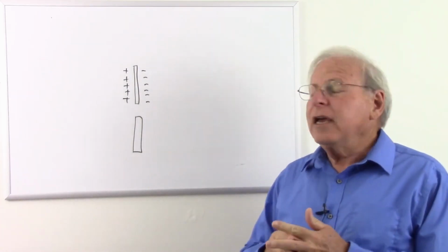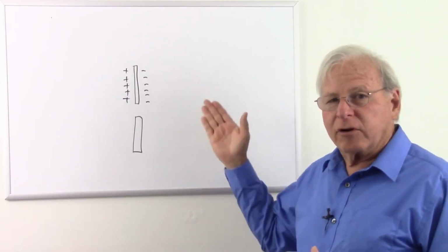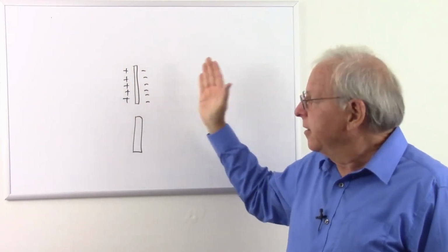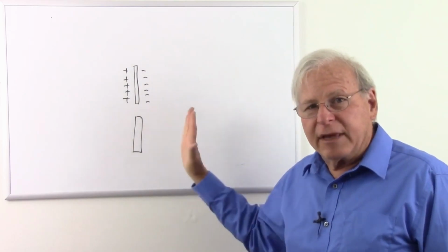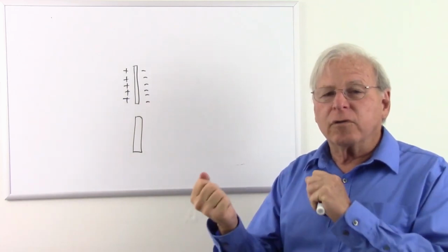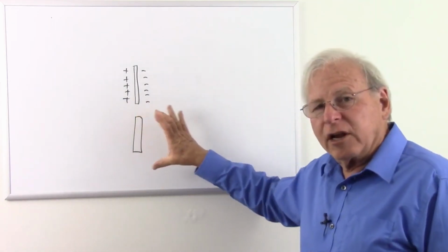And where you see this used is first in crystal microphones. I'm going to talk about that first because it uses the distortion factor, and that if you talk on a crystal microphone, it makes it vibrate, and that causes it to develop alternating voltage of positive and negative voltages, and that can be channeled off with wires.